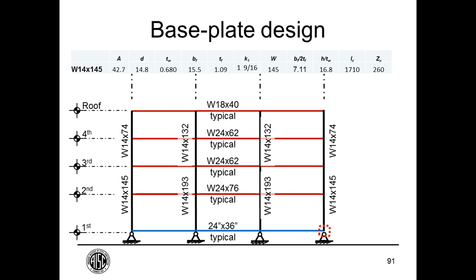And I don't see that as a very realistic way of designing for the base of a special moment frame. So it's probably conservative for selection of your beam and column sizes, but in the end you have to design that connection to perform under large lateral loads and large lateral drifts. And so I don't see how you can actually accommodate that inelastic rotation in a so-called pin connection.